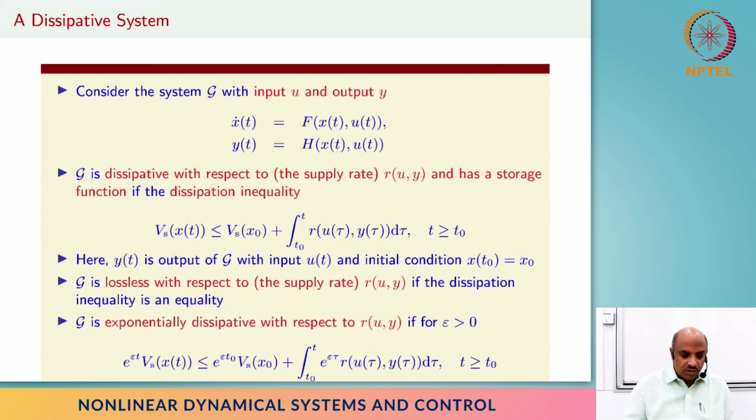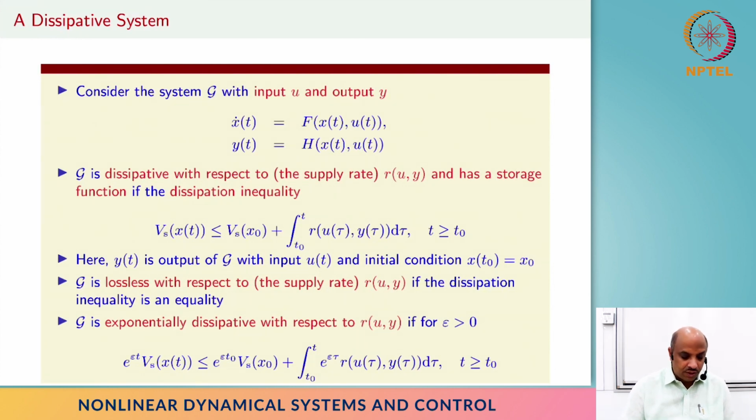Okay. Now there is an additional concept, and you can blame it on my dissertation. Basically, we define something called exponentially dissipative, and this becomes very useful in designing controllers and things like that. Or some plants, some systems have this feature naturally, and it's simply an extension of what we see in the dissipation inequality with an exponential weight, and it has certain implications which we will discuss a little bit later. But it turns out, if you're curious, if you recall positive real versus strict positive real, this is the strict positive real version of the dissipativity.